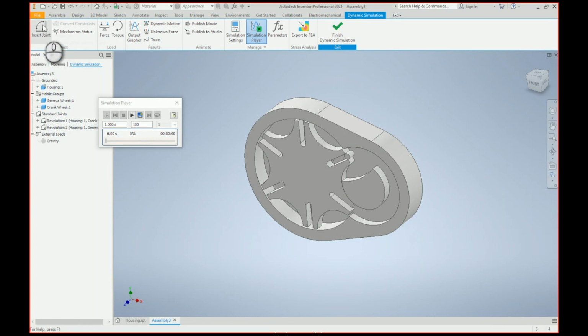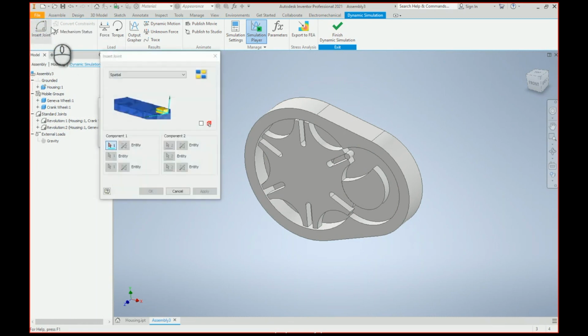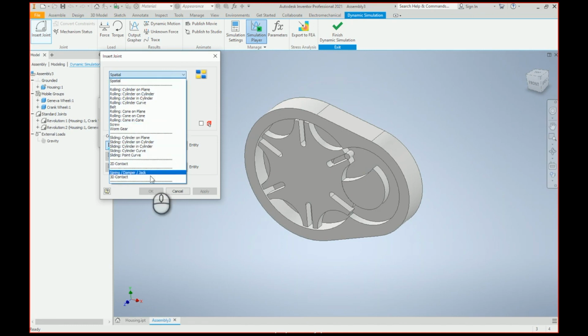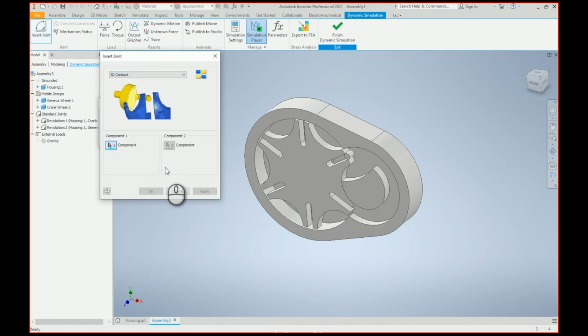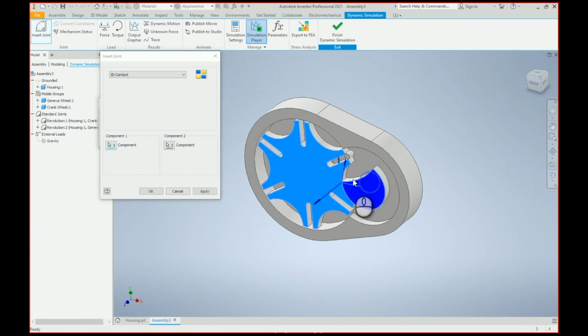Now let's add a force joint, "3D contact." This is a very interesting joint. It makes the pair of objects behave like real-life solid pieces. In it we can set all the properties, like friction, stiffness, etc. It makes the contact of the pair very real. In our case, we are not going to set any of these parameters. Like I said before, this exercise is just a representation of the movement, and we are not getting into the dynamics of it. Select the first object, and the second.